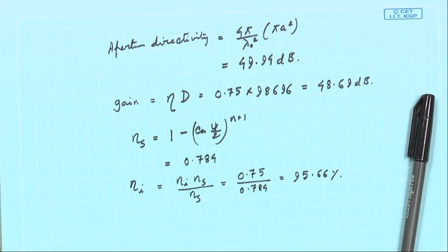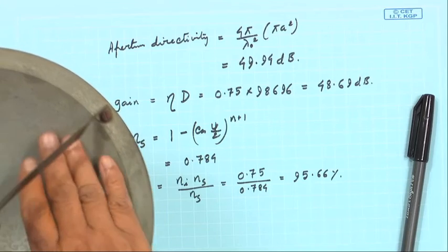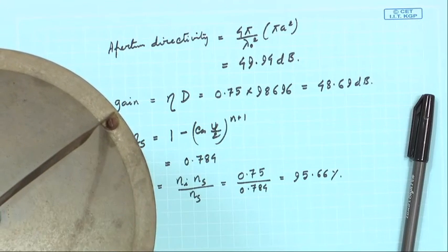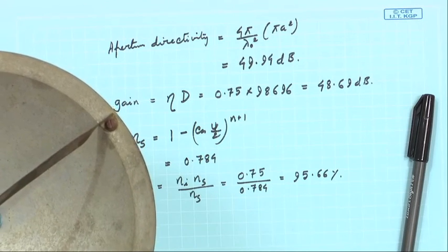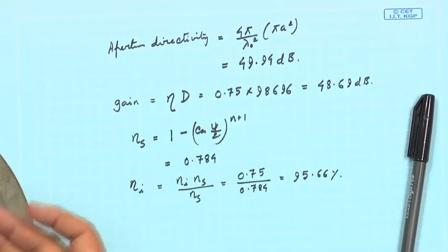Okay. Now, there will be other efficiencies also which we have not said. One of them is the surface roughness. You see here the rays are coming. If the surface is rough, then there will be some error, because here we are assuming that the rays are regularly reflected, but due to the surface imperfection there will be scattering. So, that is specified in terms of surface error.